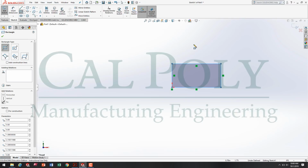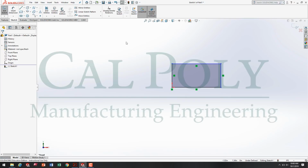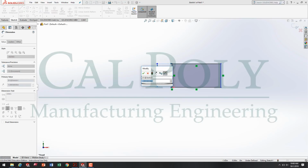Then, it does not have a size dimension associated with it yet. It actually does, 1.0 inches. However, we want to lock that in using Smart Dimension or define it using Smart Dimension. So I click on my Dimension tool up in this top left corner, Smart Dimension, and I click the vertical line, and drag outwards and click my mouse button again.